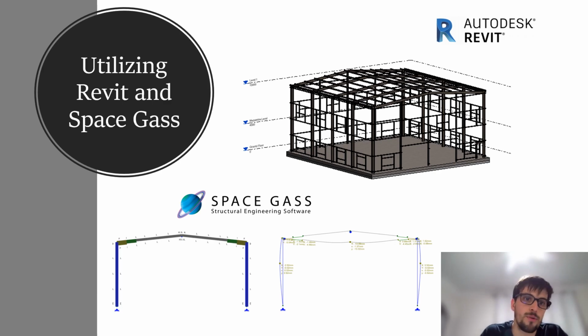First, the model of the portal frame structure was created in Revit in 3 dimensions. Revit is an Autodesk design software that is useful for civil engineering design. Using Revit, the slab substructure, steel columns, rafters, purlins, and all connections and finishes were designed and are pictured here.